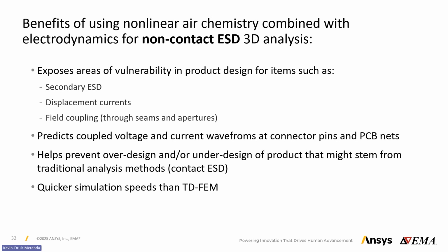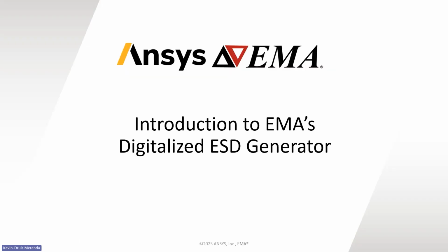So instead of idealizing the waveform for an ESD that you typically may get from a standard, in this case, the ESD is really dependent on the gun and the device under test. And so we really have to consider these two to get the actual current waveform onto the system. So this can help us limit over-designing diodes based on just an idealized waveform and make sure that we properly get the right current that is passing onto the system. It is a quicker simulation speed than the FEM, but it is, again, limited to air.